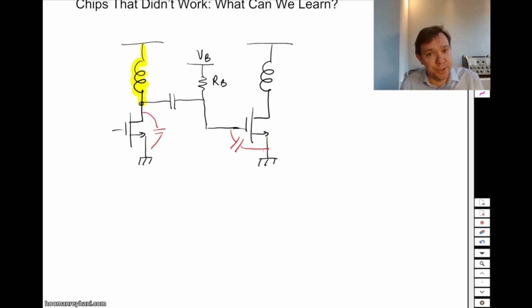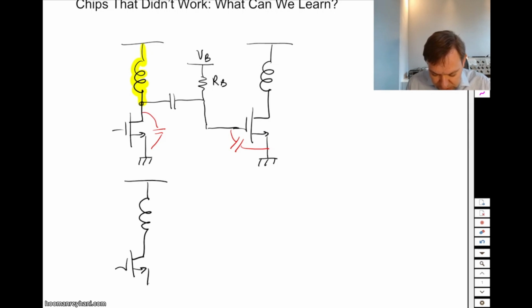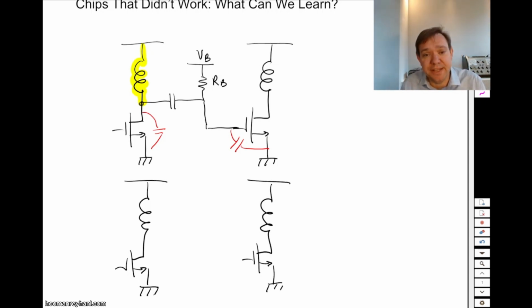Whereas if you go to much higher frequencies, another approach is typically followed, where you have a first stage, and again a second stage, and they can have different sizes depending on whether we want to maximize the gain, the output power, or minimize the noise. In between I can put a matching network, and matching networks are interesting. They do consume quite a lot of area, so you have to be careful with that constraint, but they are interesting because a matching network or an impedance transformation network gives you voltage gain. Obviously it doesn't give you power gain, it actually gives you a little bit of power loss.